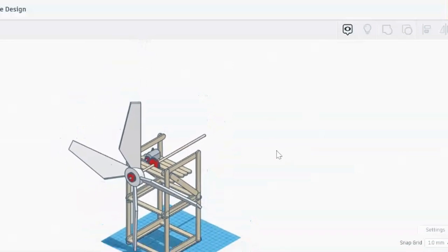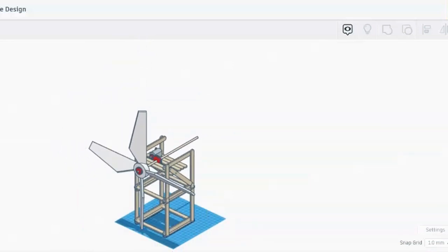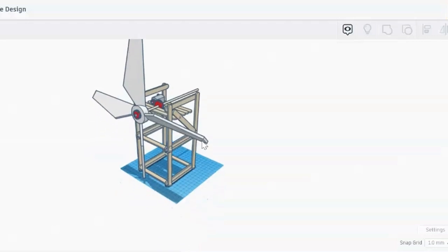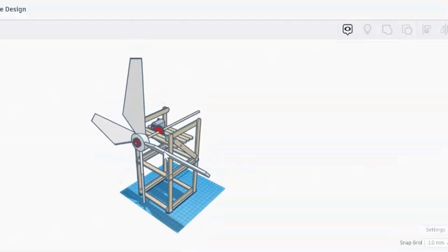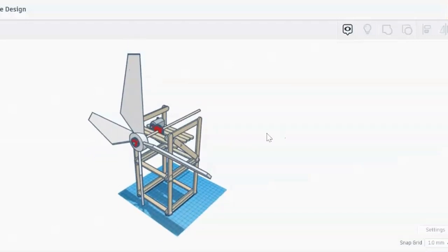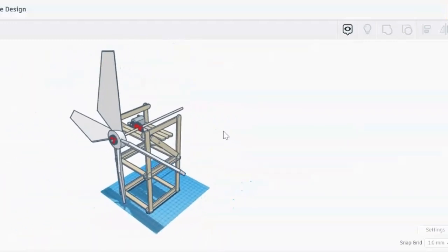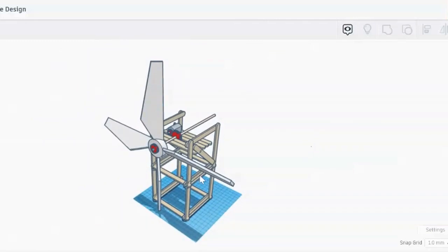But you'll notice it looks kind of funny. It looks out of perspective. And that's so if you are not viewing an object directly head on, you're going to want to switch back to perspective view. And now you'll notice it makes more sense. Again, I can use my middle scroll wheel on my mouse. If I click it and hold down, I can pan. Again, this is not changing the object, just changing the angle from which I see the object.